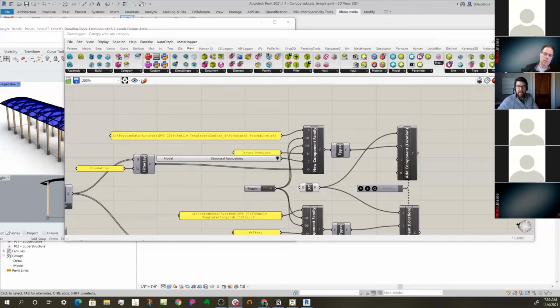The reason I'm going over this is it's very important that you understand that hierarchy when you're using Rhino inside Revit. In Revit, you have categories. Categories contain families. Families are just the definition. They don't exist in the view yet. And then you have types. So you always have family, type, instance. And you're always going to want to use that.